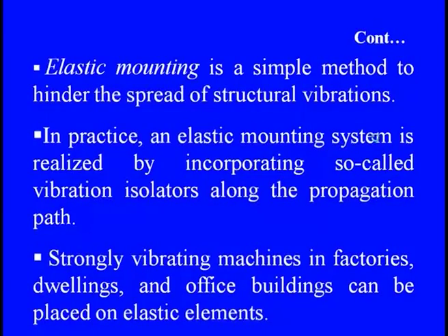Then certainly you see here that the vibration generation as well as the noise is so significant, and the transmission of these vibrations is rapid, because these heavy machines are always mounted on the solid surface, so the transmission of vibration and noise is so rapid that the entire office buildings can be damaged. So we need to apply some elastic elements along the walls or on the foundation or in between the machine and the rigid foundation, so that the transmission can be avoided or eliminated from the source itself.